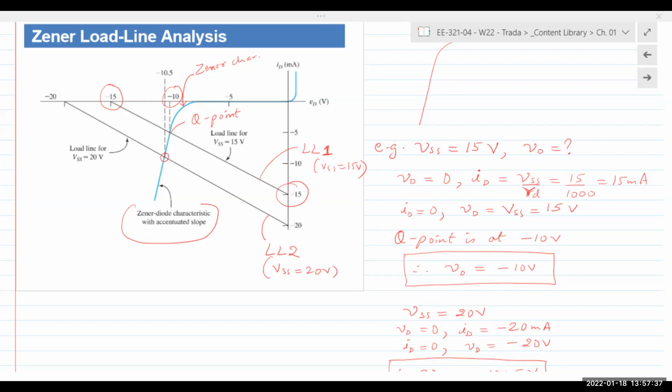So our DC level, let's say it's here, 0 volts. And this is our, let's say, 12 volts. And we have ripple on top. So there's still some sort of AC component along with that DC, right? So like a maximum peak of 12 volts. Now we connect a Zener diode of 10 volts at the output of the rectifier circuit.